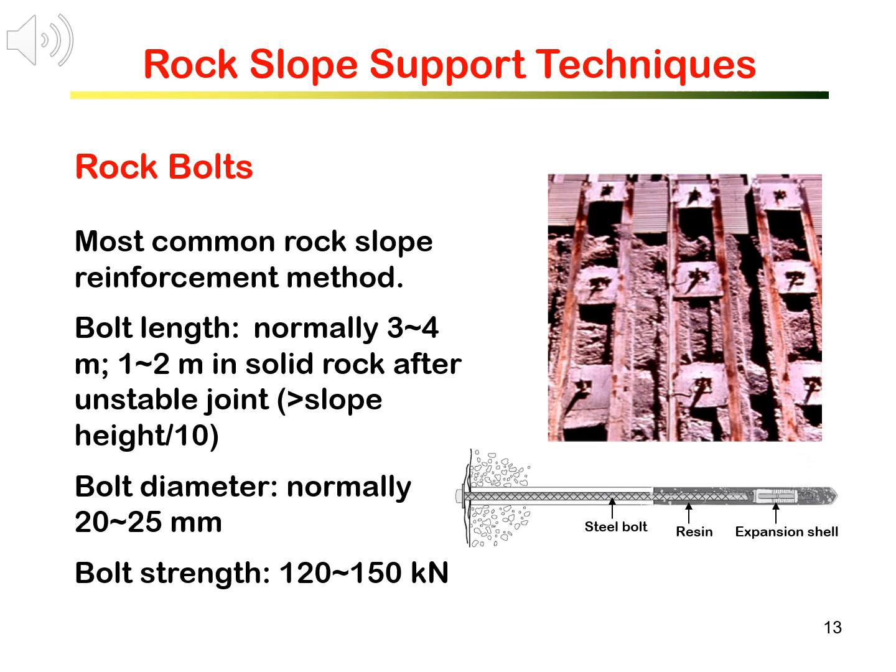Steel dowels sometimes are also used for rock slope reinforcement, and they serve a very similar function as rock bolts. Bolts are normally about 3 to 5 meters long, and they are designed to have 1 to 2 meters in the solid rock beyond unstable joints.